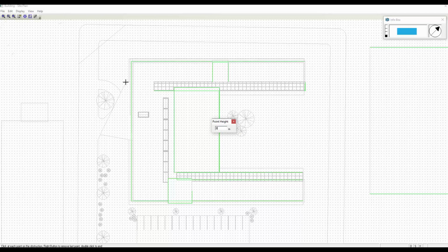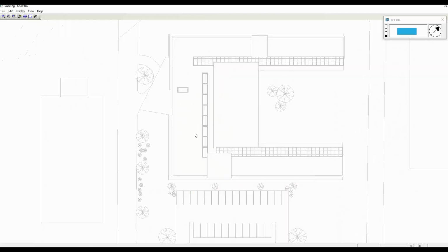So I'm going to make that 8 meters. I'm then going to put the pitch on the angle and make that 12 meters. That's going to be 12 meters. Switching off my orthogonal so I can do the non-orthogonal line. That's at 12 meters. Then we go back to 8 meters. Click on the start point. So that's created that shape.